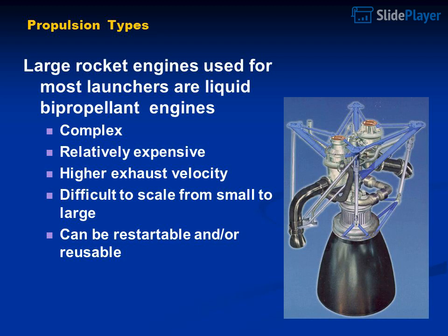Large rocket engines used for most launchers are liquid bipropellant engines. Complex. Relatively expensive. Higher exhaust velocity. Difficult to scale from small to large. Can be restartable and or reusable.